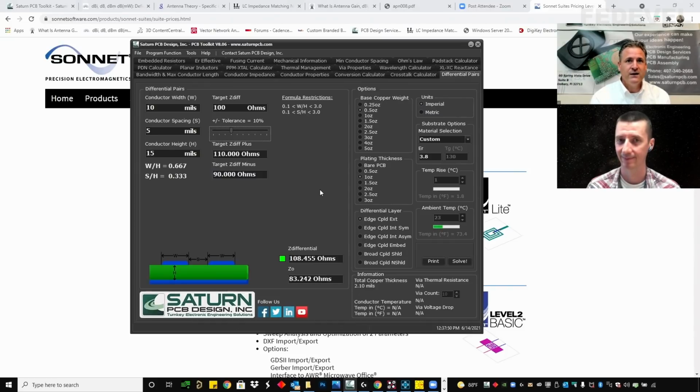Yeah, I did PCI 3.0, which is 8 gigabit, on a pretty high-end board we did a couple years ago. And they were very long differential pairs. I think they're like 8 or 10 inches long from end to end of the board. And I'm thinking, oh great, this is going to look ugly, because the customer required that I do post evaluation. So I had to rent this Tektronix oscilloscope, this $500,000 oscilloscope with differential probes. And I fired that thing up, and I'll tell you what, the eye diagram was crystal clear.